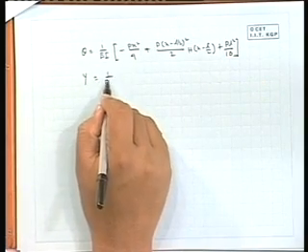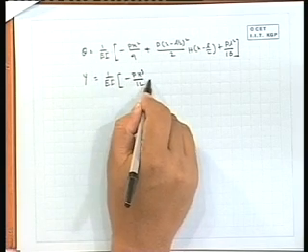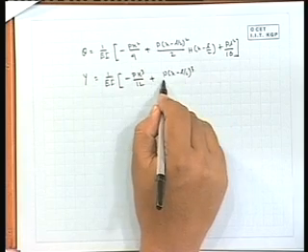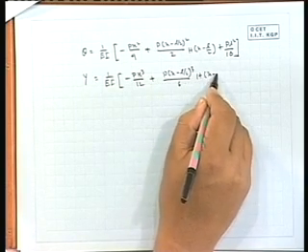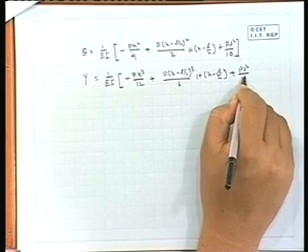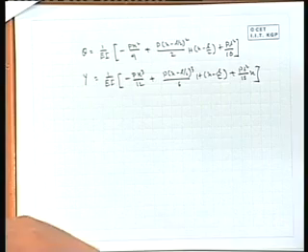And y will be 1 by EI, P x cube divided by 12 minus P (x minus L by 2) cube divided by 6, right. So, whatever expression we have derived, just the value of C1 we have substituted. The 1 by EI part I have brought out here.